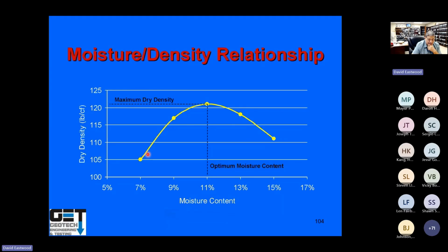Again, in our pavement design, we assume a strong subgrade. We assume you take these soils and stabilize them with lime, fly ash, or cement. So it's very crucial that you get a good Proctor on it. That's the optimum moisture. This is the maximum dry density here. You want to compact to 95%, which is 115 pounds per cubic foot, at moisture content plus or minus 2%, which goes all the way from 9 to 13%.